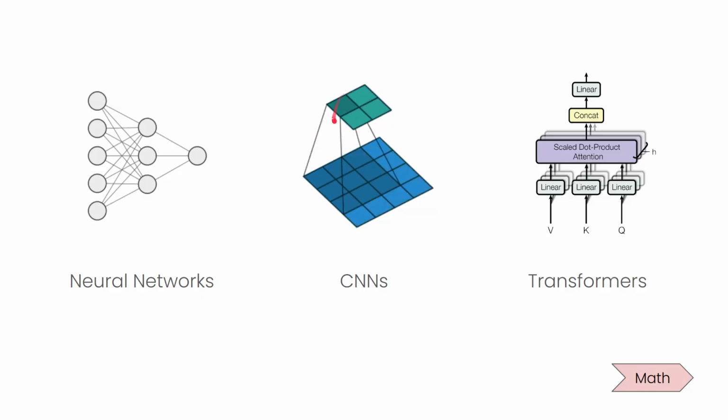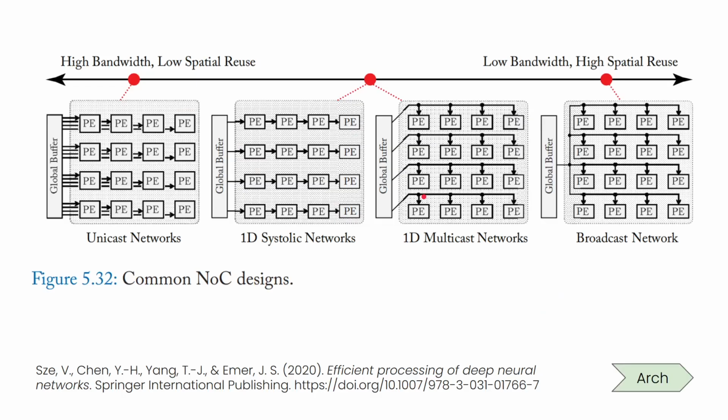You have, as you can see, this one filter being applied in multiple positions. So these same filter weights are applied to different regions of the input activation. So the same weights, those same numbers, that same data will end up multiplying different input activations. Well, that's why it would be good if you could, for example, distribute the same weight here. And you saw that CNN filter had four placements. Well, distribute that same weight. You have spatial reuse there.